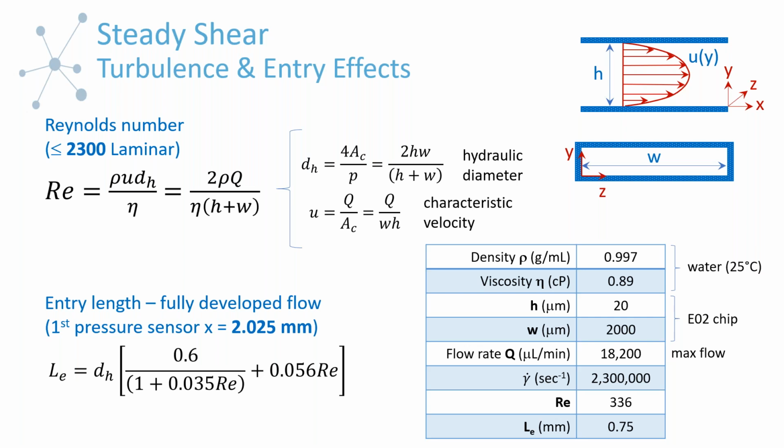So I wanted to point out that, if you're concerned about predicting whether or not you'll have turbulence in our microfluidic geometries, you can look towards the Reynolds number equations, which is basically looking at inertial to viscous forces. So when Reynolds number is small and viscous forces are dominating, then the onset of turbulence or the onset of secondary flows isn't going to occur.